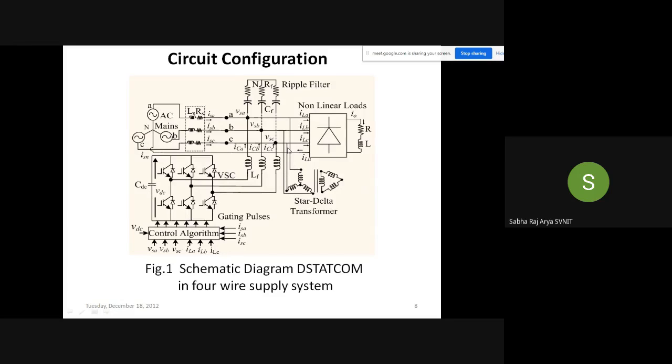This is a passive arrangement. By a simple transformer connection also, we can compensate the neutral current. Okay. But if you want active compensation for neutral current, then you can design a 4-leg converter. But here we have a 3-leg converter only. With 3 legs, you can solve 3 problems: reactive power, harmonics, and unbalancing. First requirement is that you maintain the DC bus voltage at least at the peak value of the line-to-line voltage. That is our requirement. That much you can maintain.